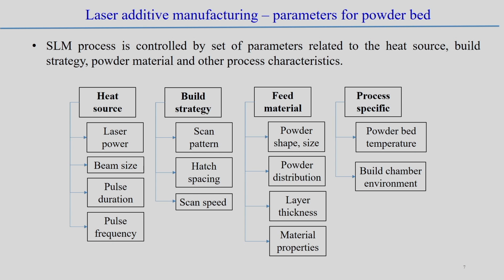Not only this, the scan speed also matters, how fast we can move from one point to another. It mostly depends on the heat input power per unit length during this particular process. So, it depends on the laser power being utilized; accordingly you can decide the velocity, how fast we can move to develop this product.